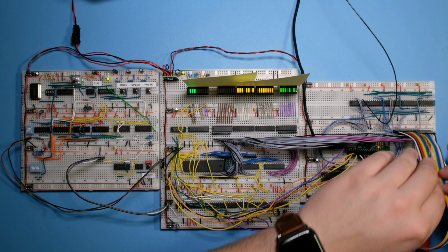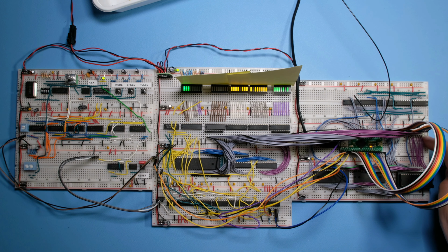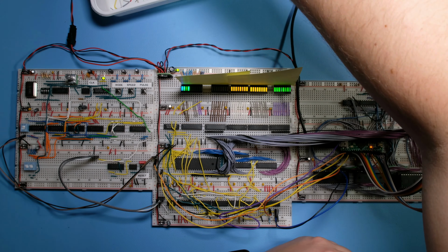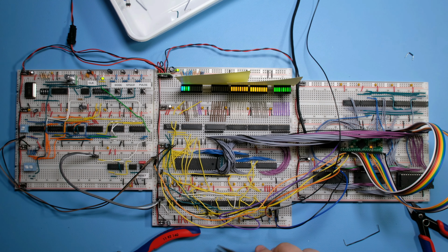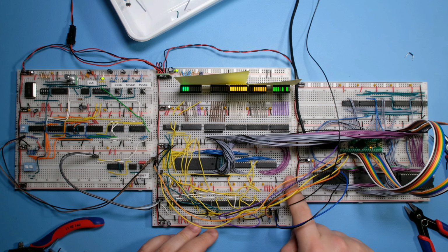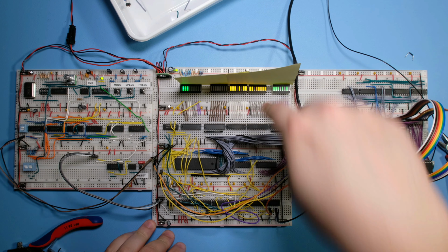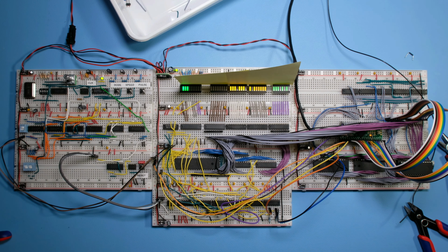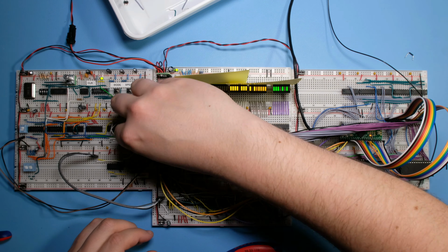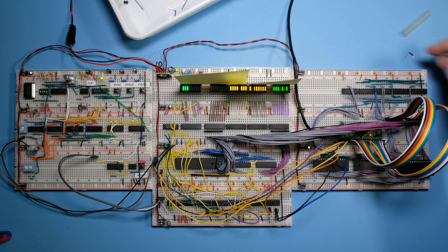There we go, and then we need to ground this here. And then from there, it's going over to here. So what I would really need to do is actually connect the ends here so that the ground has a way to go. And I guess I can do the same here. And these ones I don't care. And I'll do the same here. There we go. And so this should have improved our signal integrity massively.